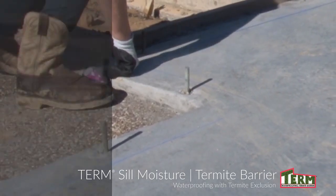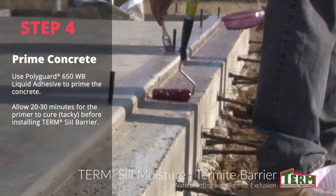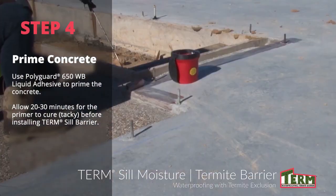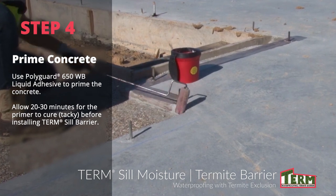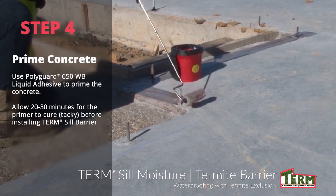To prime the surface area, apply Polyguard 650 WB liquid adhesive to all surfaces which will receive the TERM Sill Barrier. Allow the primer to cure until it is tacky. This is usually 20 to 30 minutes.